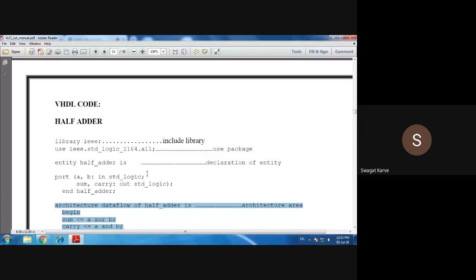Process statement. Very right. It should contain process statement. Then you can recognize that it is a behavioral style of modeling, right? So this is how you can identify which style of modeling you have used to program any design. By looking at the program, you can easily find out which type of architecture it is, whether it is behavioral, data flow, or structural style modeling.